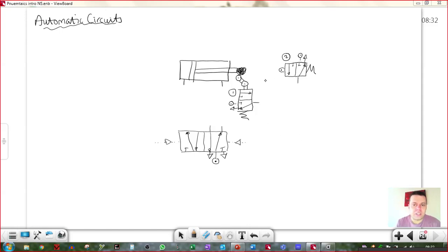And this is where you see why we have these different actuators and maybe less common actuators. So consider this system that I've laid out here. We've got a double acting cylinder, A, connected to this 5-2 valve, and the 5-2 valve is a pilot. We've got two different 3-2 valves here: a roller trip spring return 3-2 as valve 1, and a plunger spring return 3-2 as valve 2. You can see how we've positioned them, in such a way that the cylinder will actuate the valves as it goes in and out. When cylinder A outstrokes, it'll actuate valve 2. When it instrokes, it'll actuate valve 1.